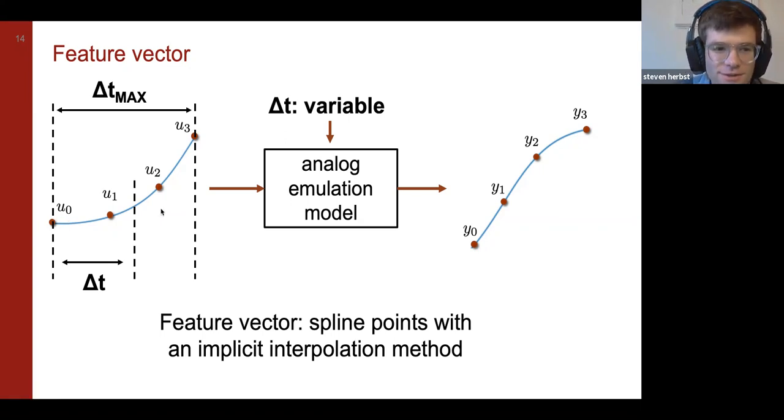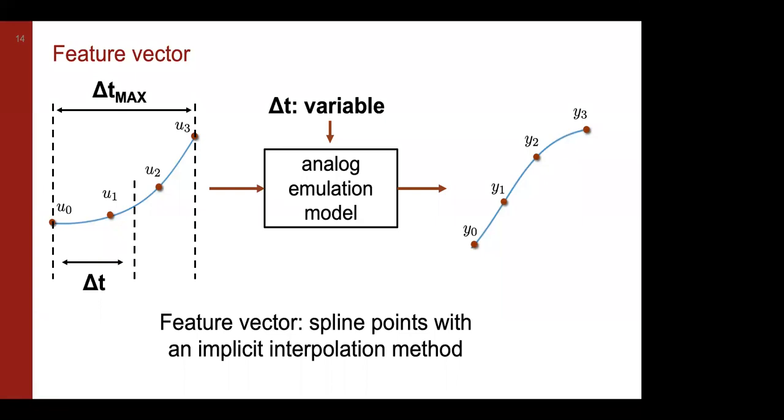But in terms of the interpolation, that's possibly an application dependent question, because if I only tell you that there are certain points that appear on a waveform, any method of connecting the dots is still consistent with that. So it's almost like there's some natural shape of analog waveforms described by the interpolation method. The approach that I used was piecewise polynomial interpolation without any assumption about what the underlying waveforms look like. But you could also imagine that if you know there's a certain class of waveforms you're trying to represent, then given a couple of points on those waveforms, you could reconstruct the shape even more accurately than without knowledge of the shape of the waveform.